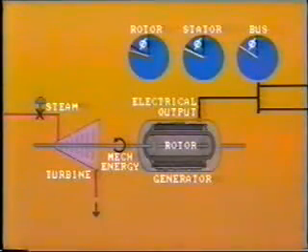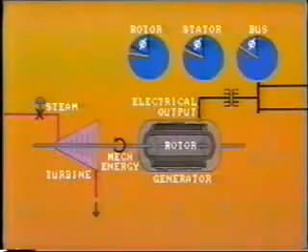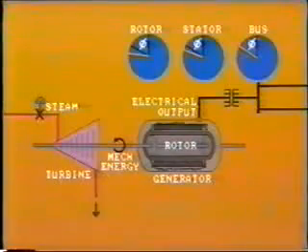There is actually a small angular displacement between this voltage and that of the bus due to the reactance of the generator windings themselves. Moreover, a transformer is often connected between the two, so adding more reactance. However, this is usually small in comparison with the reactance of the transmission line.